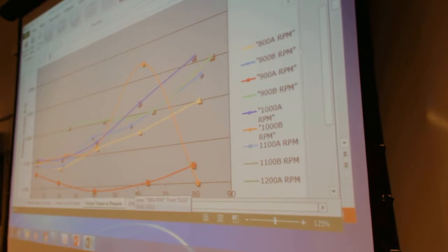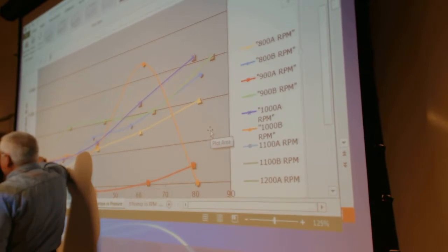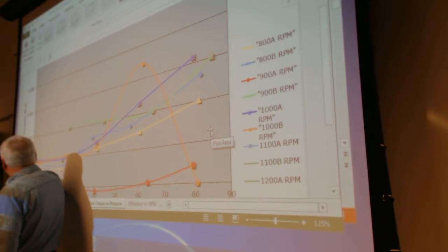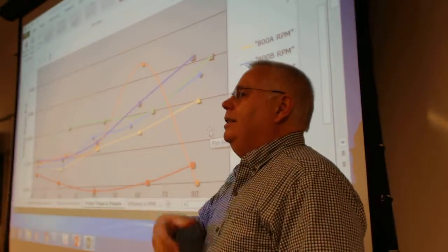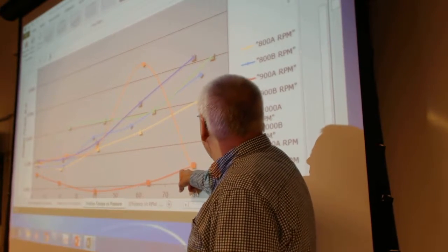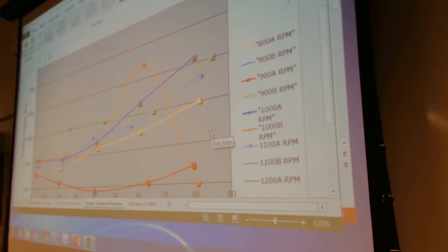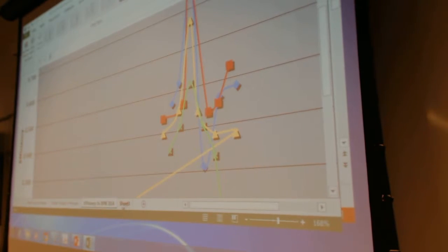And the same way, here's friction torque. If I take that power loss number and just decide it's all friction power, they're all coming down to, here's how much torque. And these are coming really close. At 0 pressure, at the low pressure, it's all coming down to 0.2 Newton meters worth of torque. That would explain the power losses that we're having. And this is an outlier for whatever reason, but they're coming together quite nicely. And efficiency versus RPM doesn't tell us anything.